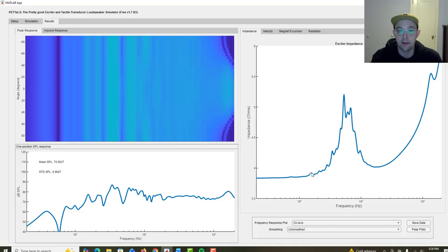So as the material gets thinner and thinner, the voice coil becomes the limiting factor in the movement of the panel, because it has the higher impedance relative to the actual panel. And then we don't even see the motion of the magnet hardly at all anymore. So the magnet probably isn't really moving at all because it's so much heavier than anything else in the whole system.